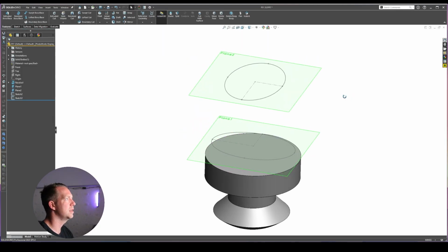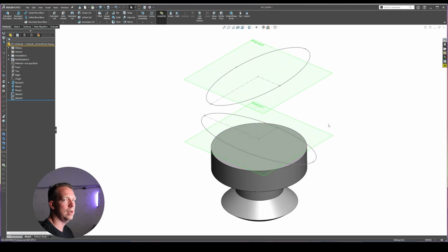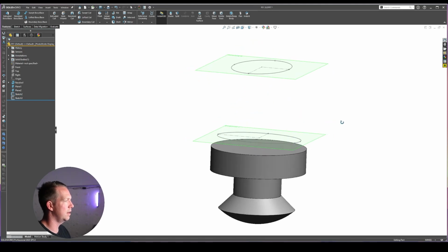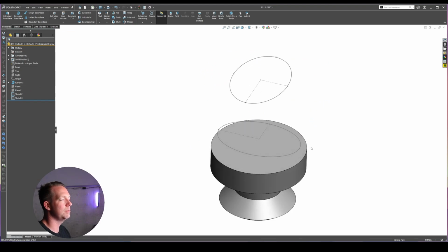Now, accept the sketch and change the dimension in sketch number 2. And you can see they're changing together. And that's how we manage the design intent of this small feature and make it more efficient as we start to move through our design. Okay, enough about sketch tricks. Let's hide those planes. Don't need them anymore. And we now have 3 profiles set up to do our loft.